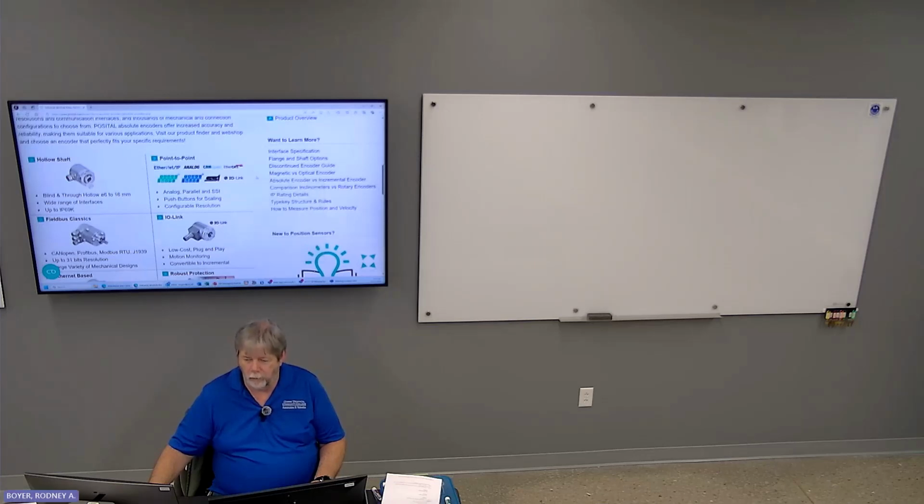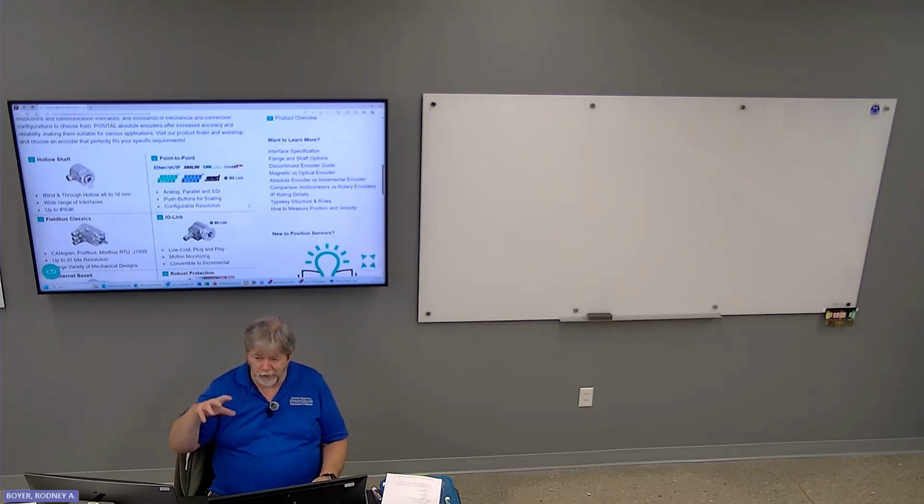You can do distance and all kinds of things over IO-Link. Instead of just getting an on or off signal, IO-Link will send diagnostic data, like the lens is getting dirty on your laser sensor, and things like that.